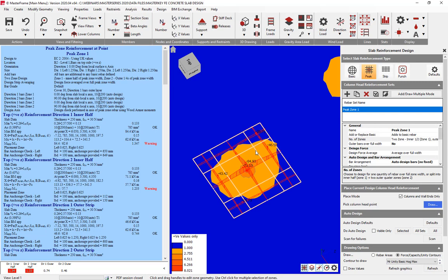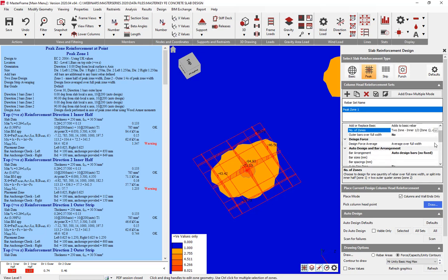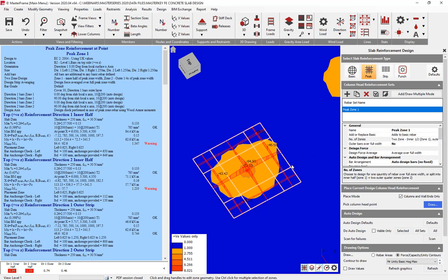The design codes of practice previously advised us when we were looking at column strips that over column heads, we would place 2/3 of the reinforcement in the middle half. So you get a slightly heavier zone of reinforcement in the middle half. And you can still achieve that type of reinforcement distribution using this 2-zone design. There are a number of different layout options available to you, which we'll try not to get into too much detail on here at the moment. Or if you want simply just 1 zone, you can do that by saying, I've only got 1 zone of reinforcement over this whole width.